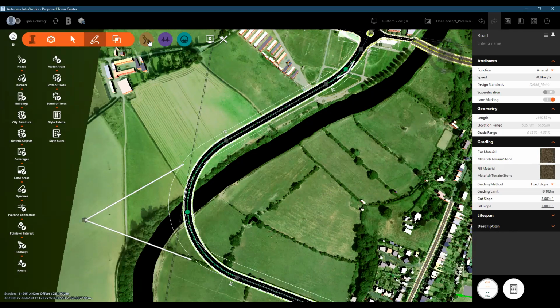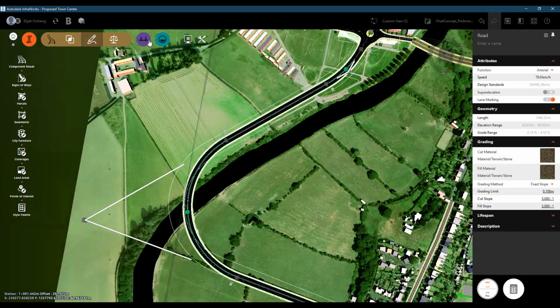So to do that with Infraworks, you go into the roads asset and you look for the analysis part. And on the review and modify your roadway design, you should be able to select profile optimization or corridor optimization. And that's found now on my asset cards, which are on my left hand side. You can see that I have profile optimization plus corridor optimization.